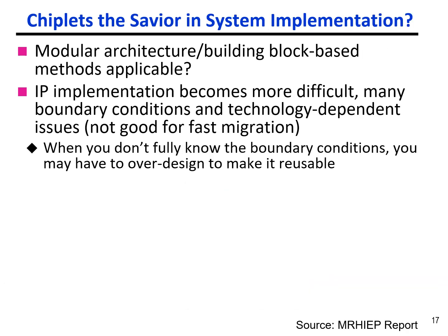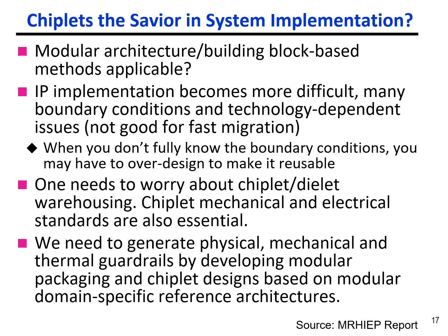So at the end, we'll show you some chiplet issues that we need to be aware of. Okay, so the basic idea is that if you don't know the boundary conditions for the integration of the chiplets, you probably need to over design and make it reusable. Okay, so we need to generate the physical, mechanical, and thermal guardrails by developing the modular packaging and the chiplet designs. So it's not that easy to just integrate all of the chiplets.